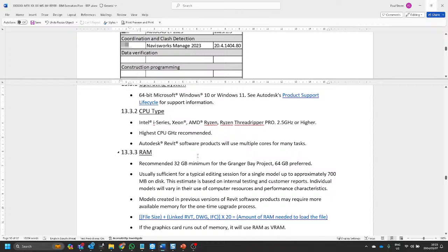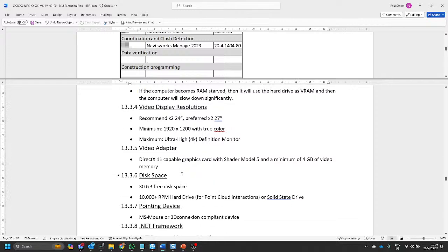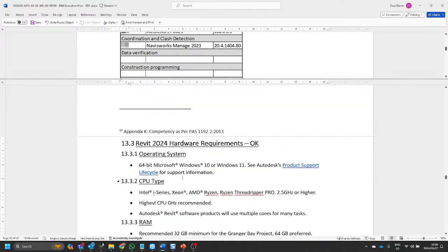So people that are knowledgeable with this process, you might even say, look, I need efficiency on this project. What that means is that when you guys are working with the files that you're supposed to be working with, you will have the correct hardware, or otherwise you're wasting my time and my money, putting the project at risk because the project is going to be late because your computers are not up to standard. Specifying that in the exchange information request, responding to that with a BEP will then ensure that contractually, once you sign the contracts, that whoever is on the project will have the correct hardware to do that.